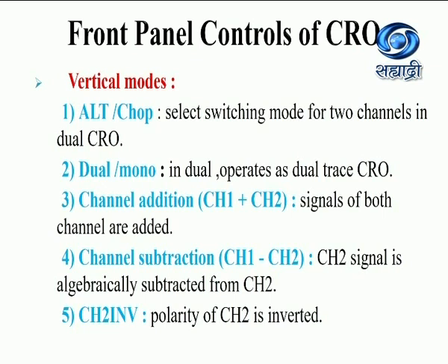Then fifth one is channel 2 inverted, that is CH2-INV. Polarity of channel 2 is inverted. So when we want to invert our channel 2 signal, then we can press this control.